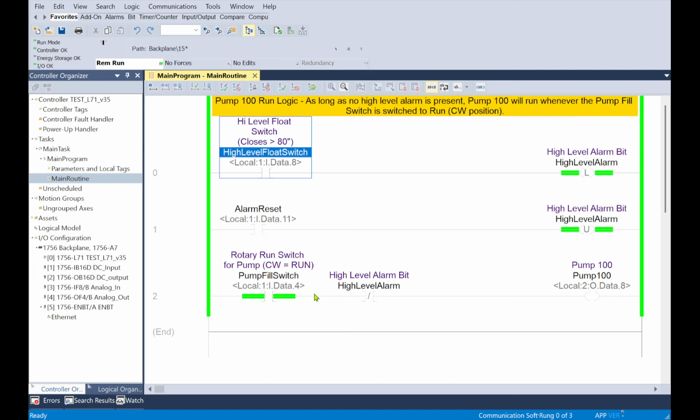And in many actual control programs, there might be 10 or 20 of these conditions, permissives if you will, in front of a certain output. And that's normal. That's ladder logic. That's what it's replacing, old relay systems.